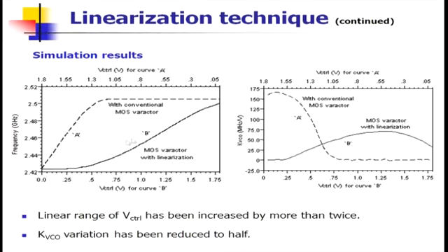So now if you have that common source stage, then what is happening? It becomes a little sluggish. So your slope is less, that means KVCO is less. If KVCO is less, that means your noise performance would be better. So there is a small change you made in your conventional cross coupled LC oscillators. So that is the KVCO without this stage, and this is with that common source stage, that improves it to a much lower KVCO, where it goes to 50 or 60 kind of megahertz per volt, but the maximum it goes to around 70 megahertz per volt just by introducing a common source stage.